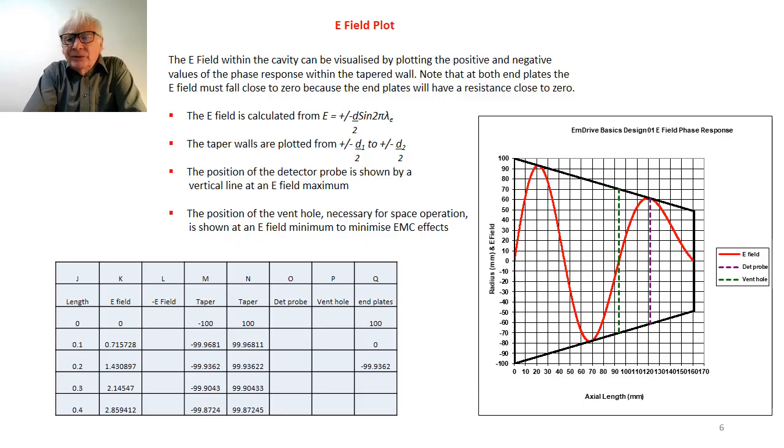You must avoid, whatever you can, a partial vacuum condition inside anything that has very high E fields. Otherwise you get breakdown. And it tends to upset the performance of these pieces of equipment, and indeed has on a number of occasions caused failure of flight equipment.